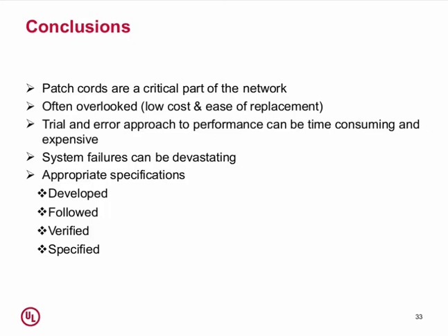Trial and error is an approach a lot of people seem to use sometimes. I'll buy a box, they're cheap, they look okay. I'll plug it in, see if it works. If it doesn't, I'll plug another one in. That's a lot more time-consuming and expensive than you might think. The other downside to that type of approach is I can try it and it'll work, but it may not be performing at the speeds that you anticipate. If I need a 6 or a 6A cabling and the cable's not performing at a 6A level, it might still work, but I'm not going to get the speeds out of it, and I might not notice that for a long time.